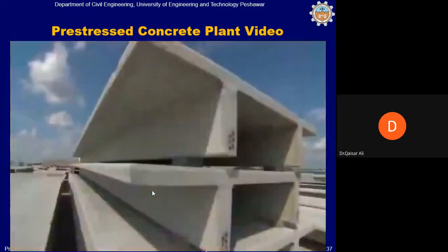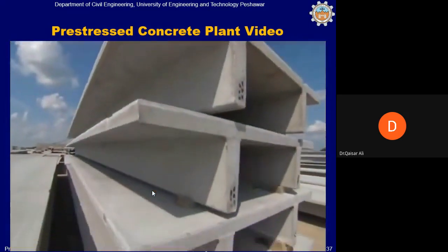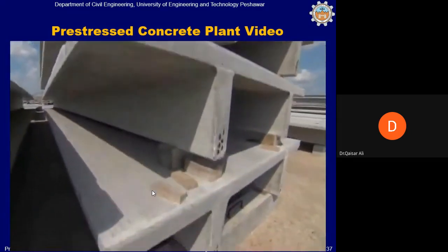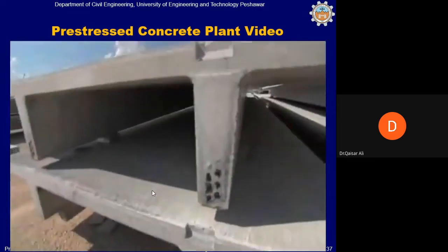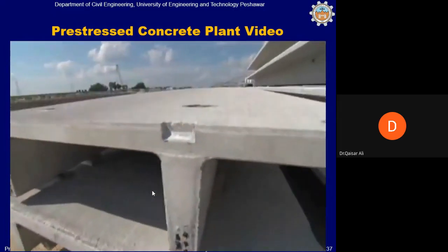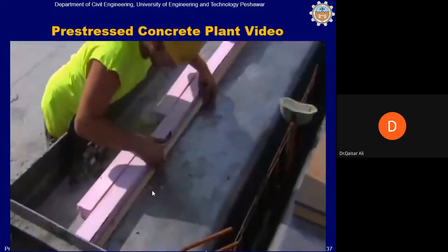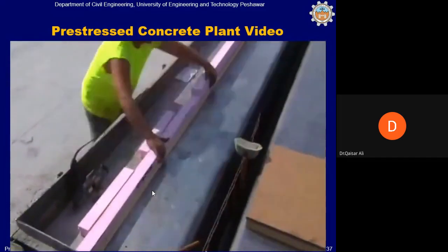Double T's for parking garages really need to be held to a high standard. When they're assembled in a garage, they make the finished surface. There are tolerances for putting these pieces together, offsets in the surfaces. All of the connections are very sensitive as well to be executed properly. The embedments in the double T have to be placed properly.